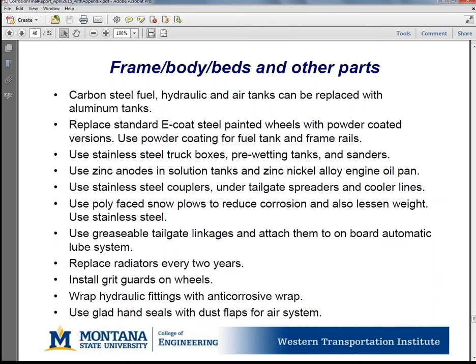pre-wetted tanks, and sanders. Use zinc anodes in solution tanks and zinc nickel alloy engine oil pans. Use stainless steel couplers under tailgate spreaders and cooler. Use polyface snow plows to reduce corrosion and also lessen the weight.